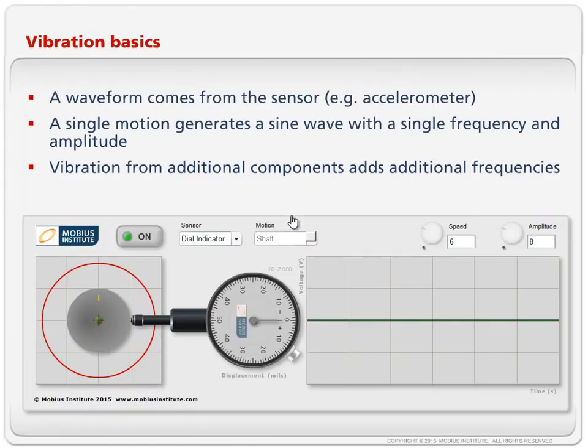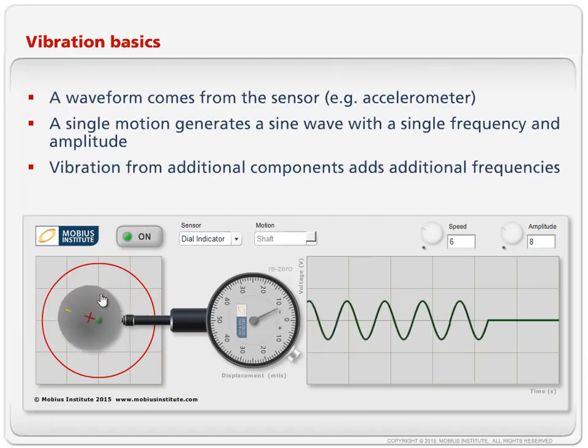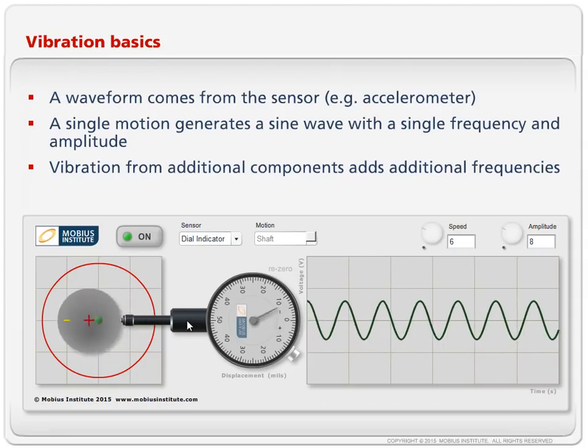Okay, so our sensor is sensing the motion, in this particular case, what I described so far, on the bearing itself. Now imagine if this was the shaft inside the machine, and like a lot of my animations that you'll see today, I exaggerate some of the motion. So there's the shaft moving around in that sort of circular motion, perhaps because of unbalance or a bent shaft. And for simplicity's sake, we've put a dial indicator on the shaft.